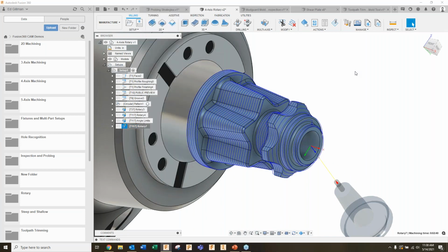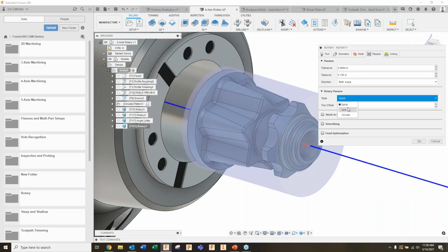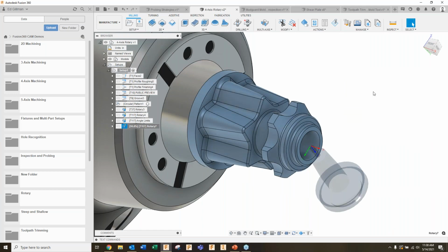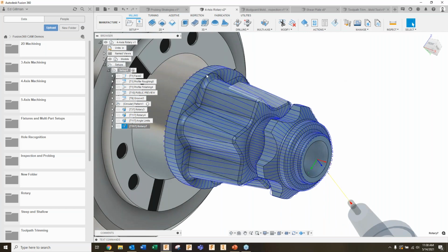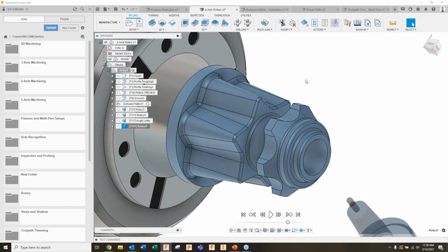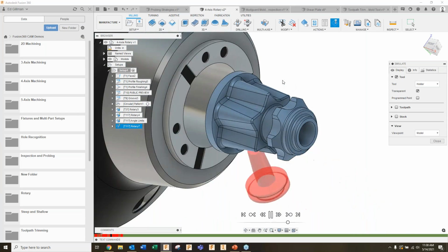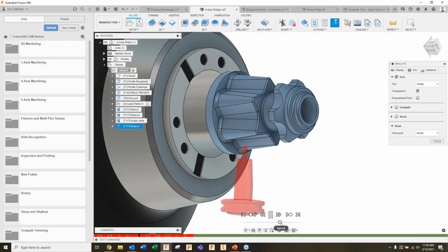Now, if you use the line function, again, it's going to switch to running along the axis. So along, in this case, the X. So a little bit different. This would be if you have a scenario where maybe you have some deep grooves along the X that you can't quite get into. You might even consider combining these two together to machine everything out, kind of do a crisscross waffle pattern. But what you'll see is it's basically going to just run along this surface, diving down into each pocket as it goes, running horizontally along the part.